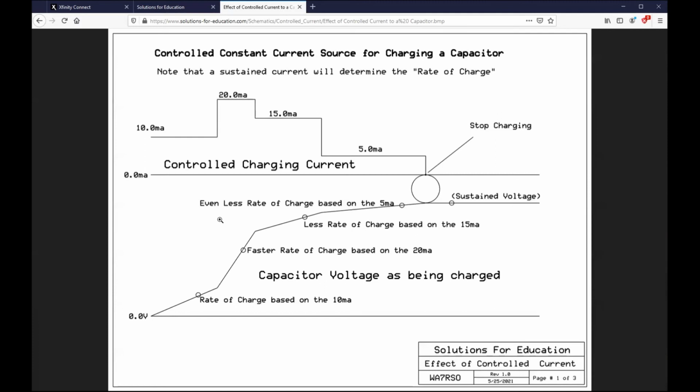First of all, what I did is I put a variac on it to bring the voltage up very slowly so that I could allow time for them to charge. And actually, I did this over a period of several days. So if it was like a 50-volt electrolytic, you'd put a variac on there and slowly bring it up with a DC power supply. Well, actually, I used the transformer and rectifier filters, the rectifier system. So I had pulsating DC. I just made sure that I had less voltage because I did not want them to come up too fast.